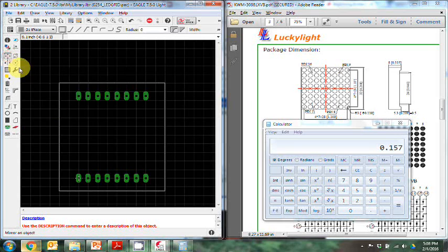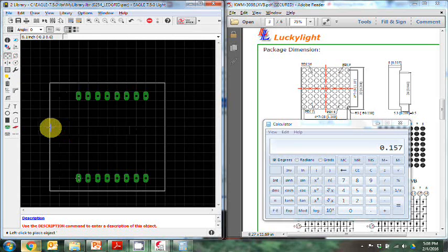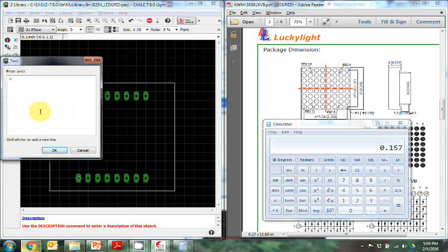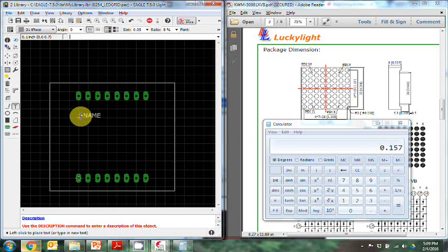So there we finished the diagram. It's just a little bit out of whack, so we're going to make some adjustments here, and that looks pretty good. That looks pretty close to what the diagram should be. Next, we want to do the same thing that we did for the schematic and add the name and value text fields. This is going to help us when we're trying to figure out which part this is when we're putting it on the layout and when we're actually assembling it. So I'm going to put the name somewhere in the diagram. It can go on the inside, it can go on the outside. We're pretty much going to use it only during assembly, so it can pretty easily be covered up.